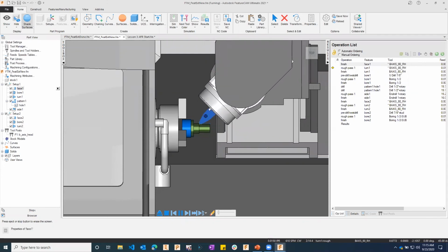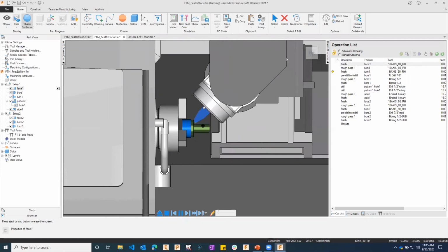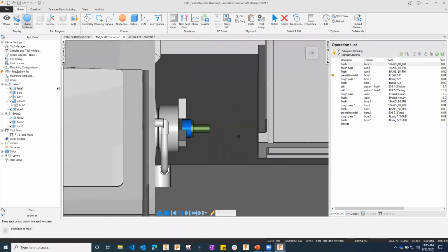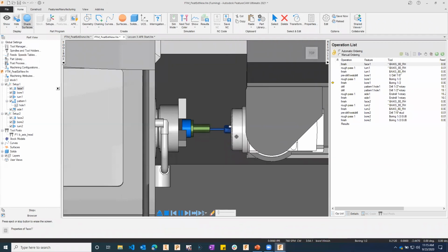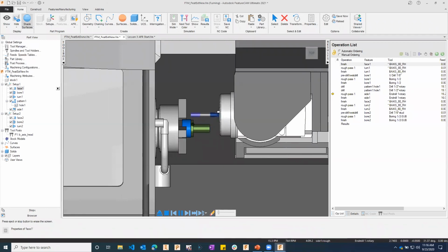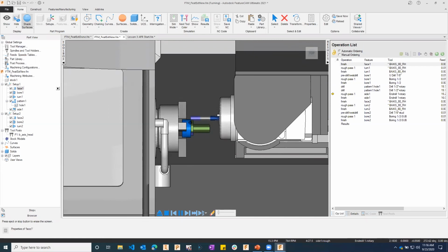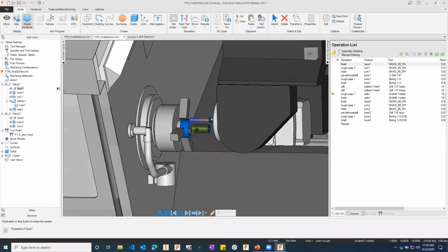All right, there we see the B-axis head rotating, doing the turn feature. Then we come in with the boring bar. There we could see it. All right, so it is rotating the C and coming in with, so it's basically doing C, X and/or Y to machine that flange with polar interpolation. So